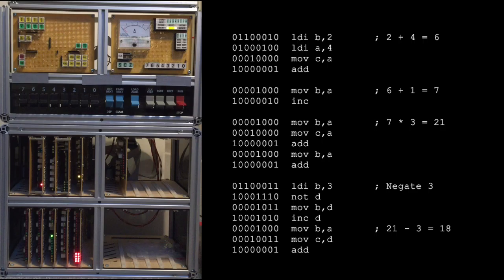OK, so a little explanation then. With the clock beating nicely, the finite state machine moves between states. Once when the clock is high, and then again when the clock is low. When it reaches the nice state, it resets because the abort 8 line is active. And this is because all the instructions implemented so far are 8 cycle.